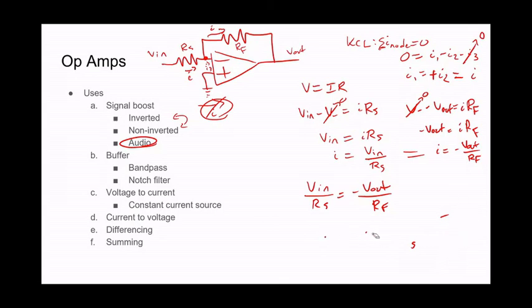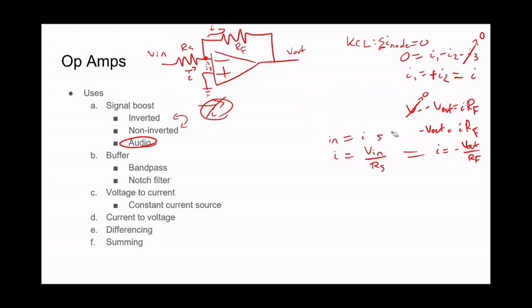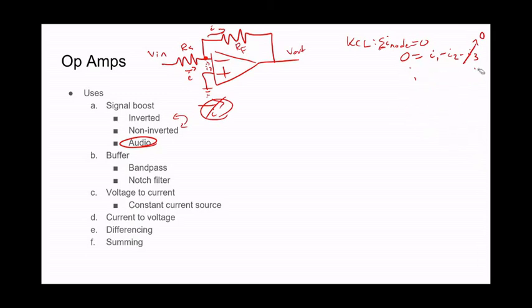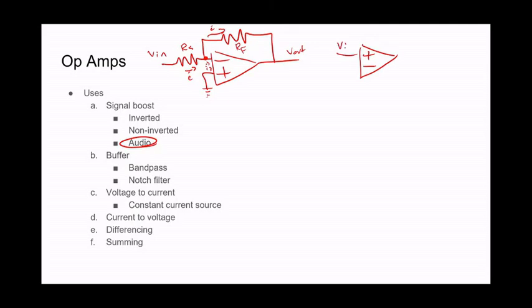But next, we're going to go over what are called non-inverting amplifiers. Because let's say you have a signal that's not a regular frequency and you want to amplify it. Now, you wouldn't be able to use an inverting amplifier because you need that voltage to stay positive. You could, in theory, do two inverting amplifiers feeding into each other, and that would definitely get you a non-inverted signal, right? Because you're negating it twice. But what we want to do instead is use what's called the non-inverting style.